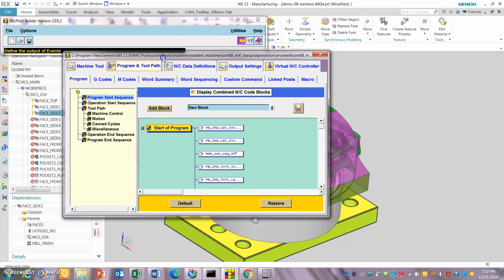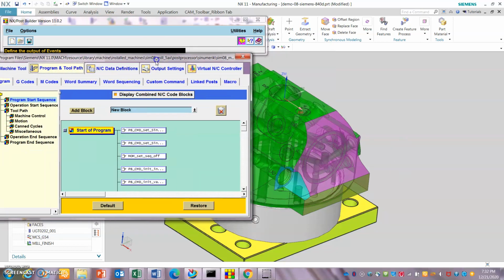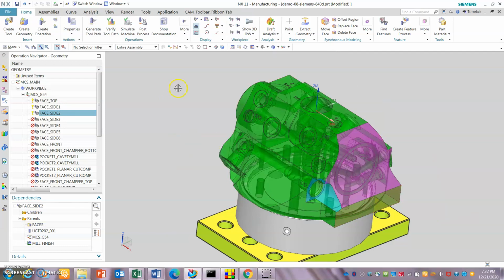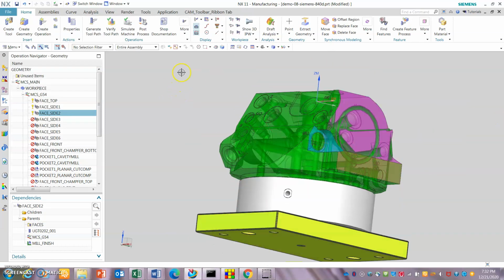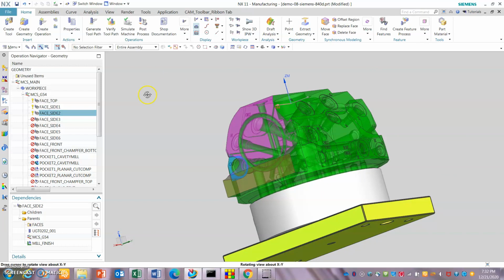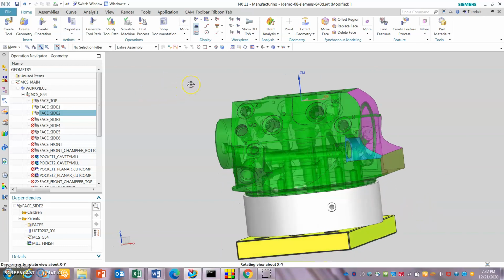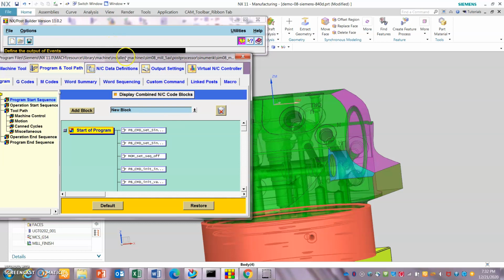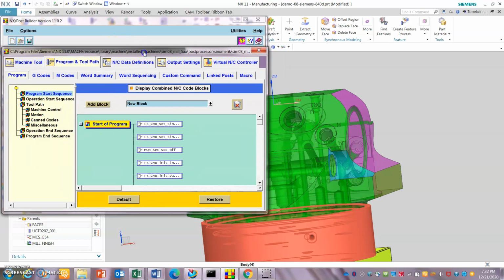The second important thing is that I pulled up a part that's close enough to show you 5-axis contouring. That's our surface, the pink surface that I highlighted. You can see that we can do 5-axis contouring where we use cycle 832, or in the FANUC it's G43.4 and G43.5, depending upon what you want to use. If you want to use the vectors.